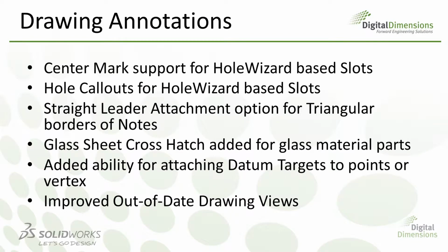Next up for SolidWorks 2014, drawing annotation enhancements include support for Hole Wizard-based slots, which have the two following items. We can now apply a center mark for a Hole Wizard based slot. This will behave just the same as sketch based slots always did in the past. But what's really exciting is this next bullet item here, hole callouts for Hole Wizard based slots.